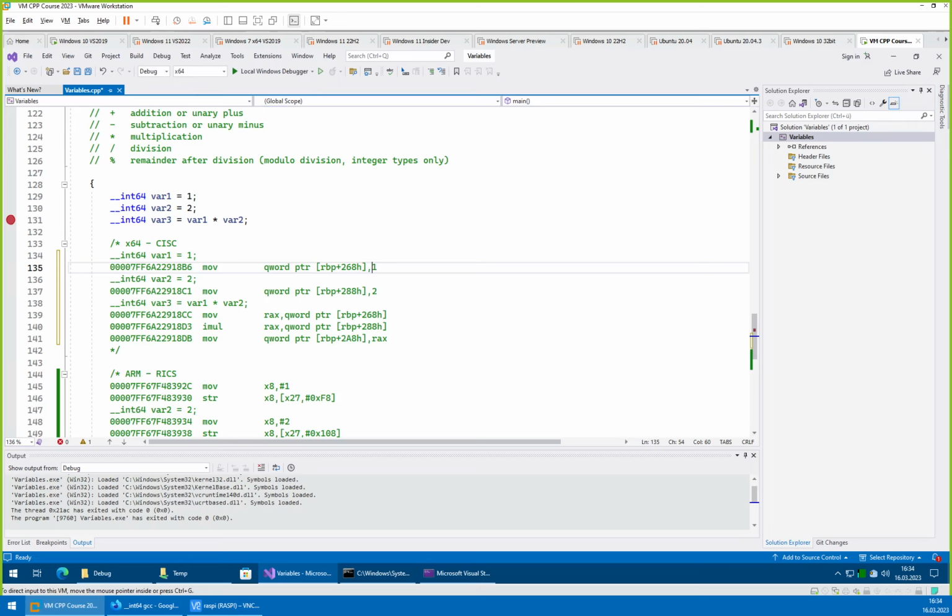While in a CISC system, you don't need this much memory bandwidth, and you really see that, for example, on multi-threaded tests, when you compare a Raspberry Pi to some other types of CPUs, you really notice that even if you get a very good result in a single-threaded benchmark, as soon as it becomes multi-threaded, because it's a small SoC and it doesn't have many memory channels, it only has one in fact, you will see that the performance tanks quite significantly.